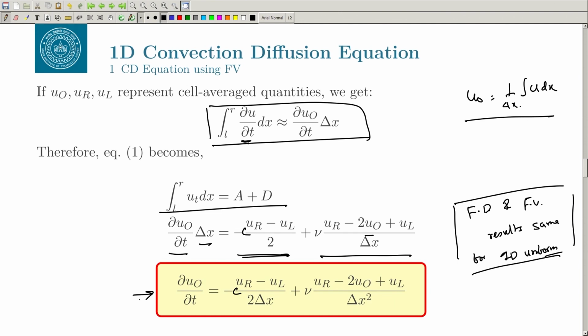Okay. You can calculate the residue on each side, each face, add it to the cell, and then finally you can time integrate it. Okay. So, here you can use whatever time integration scheme that you want. Okay. You can use the Euler forward or Euler backward or maybe the Runge-Kutta or multi-step time stepping, anything that you know.